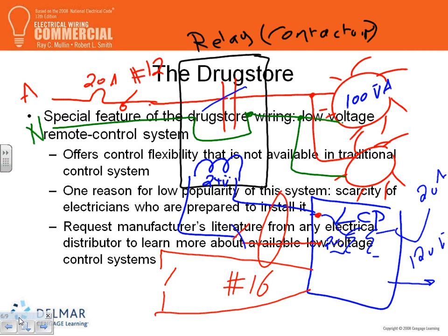Now, you have a low voltage switch here. You turn it off. Now I turn this light off. What happens if I have an emergency? I lost the power in this area. There is a switch here. It will be programmed. If you lose the circuit coming to this area, it will override that switch that I just turned, and it will turn that particular circuit on, or that particular fixture on. So there's so many ways of programming, guys.